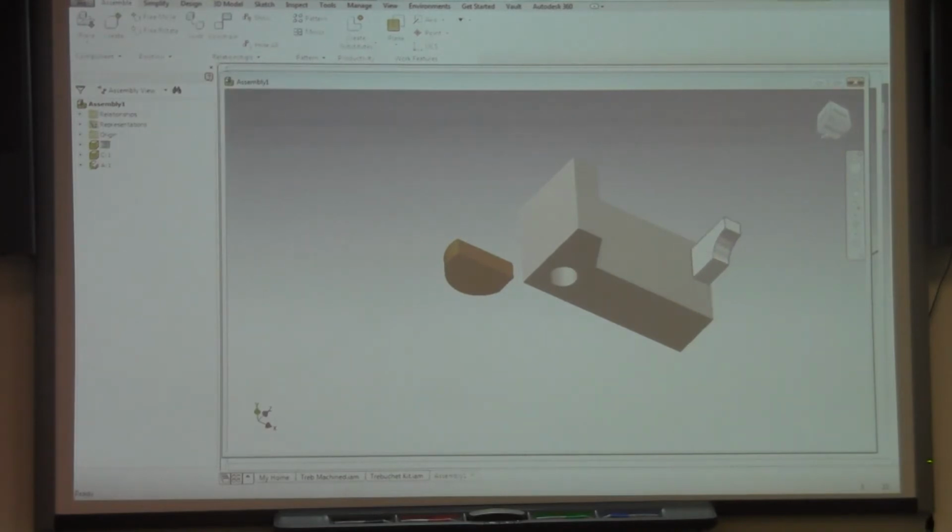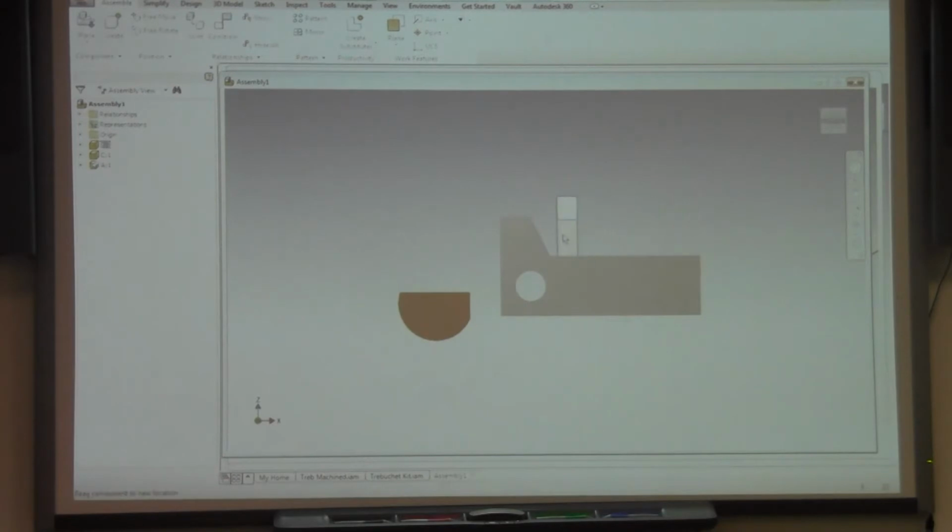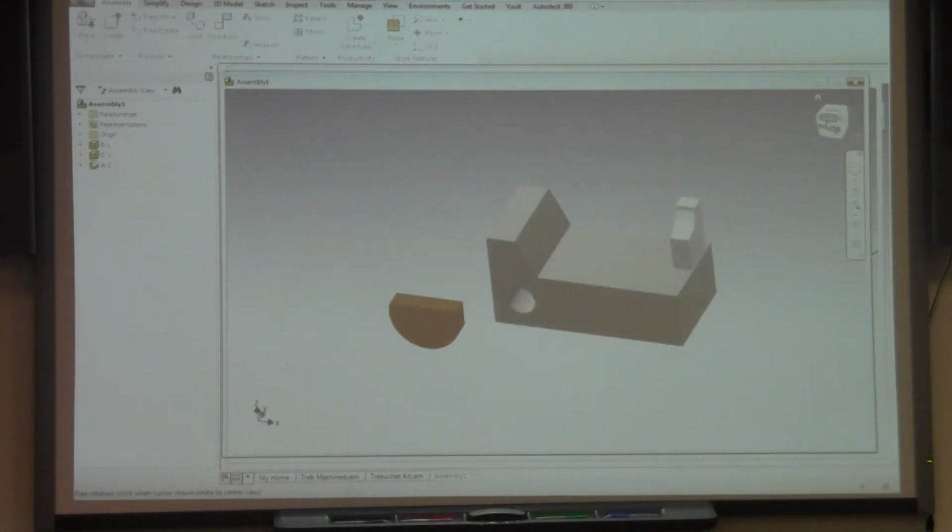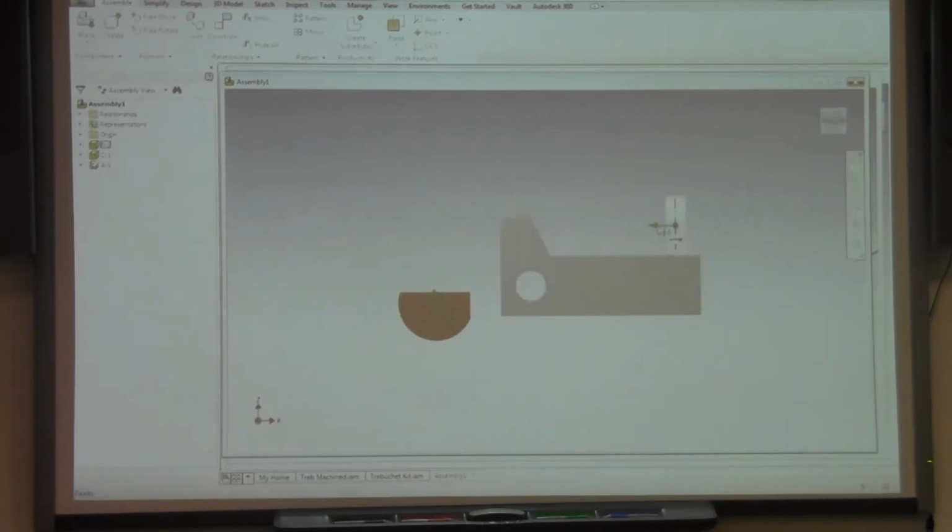Now you see, while it is glued to this piece, it's only glued in one way. I cannot lift it up. But I've not constrained it to the edge right there. I've not constrained it anywhere else. As soon as I apply more constraints, the degrees of freedom that this piece displays, view, degrees of freedom, and back to the symbol, is -1. You see, there is no up degree. If I click it this way, I can drag it this way per the green arrow. If I go to the side, I can drag it this way per the green arrow, but you'll notice there is no green arrow going up. I cannot drag it up. That is because I essentially glued it to the top of that brick.